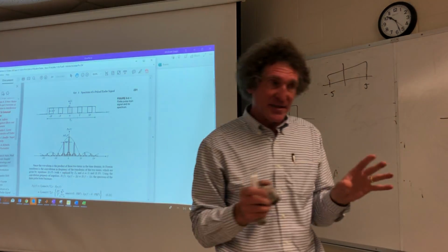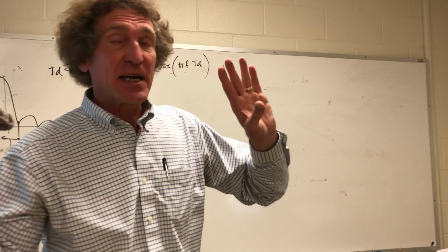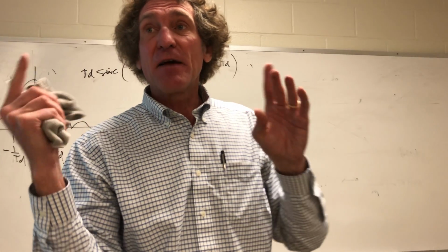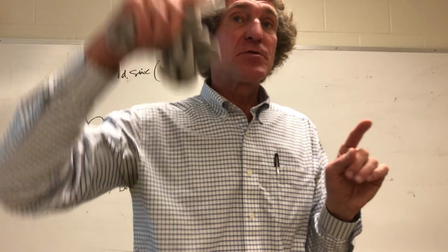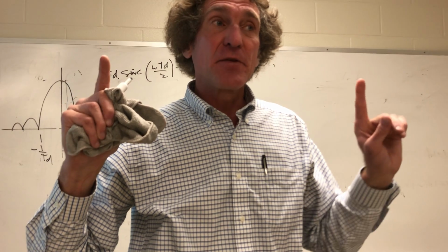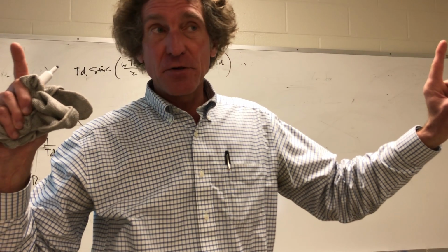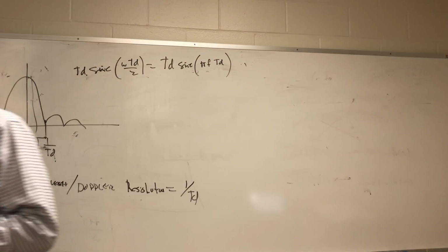But just remember that it takes a while to collect that much information, because you gotta send it, it's gotta hit the target, come back to you, right? And then you have to flip it around and do a match filter on there. And where the match filter peak is the time delay to where you are, and then the Doppler shift is observable too when they do fast Fourier transforms. We do this in chapter 14. You're gonna see some really cool stuff coming up.